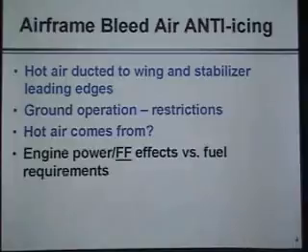Yeah. Well, wait, can't you burn it out of that 45 minutes reserve? You got 45 minutes. Isn't it legal, moral, and ethical to do that? To plan on burning your reserve? No, wait a minute, it's in reserve. If you know you're going to burn it before you take off, it's not the reserve anymore. So you cannot use your reserve to say, if I run into some icing, I'll use my reserve.